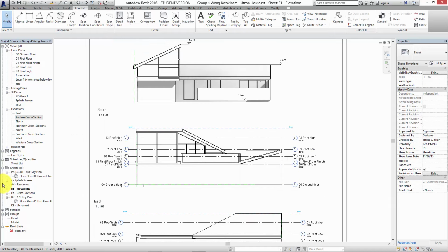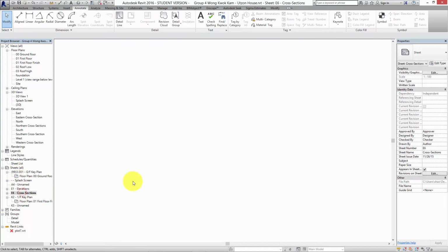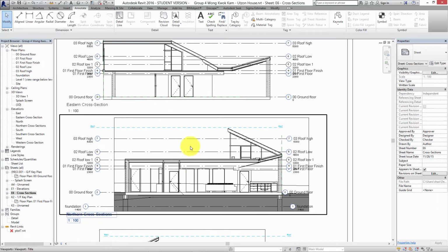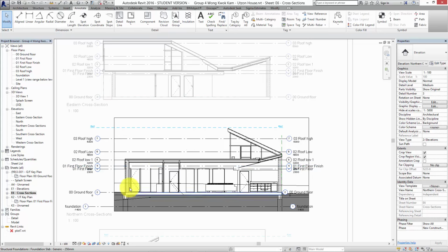Okay. What else have we got here? Cross sections. Again, I would first of all think about, is it a concept stage or technical stage, and then apply the same logic to the sections, because the client doesn't want to see the cavity wall again. Turn down detail. Oh, sorry, what did I turn it to? I turned it the wrong way. Turn it to coarse level of detail.